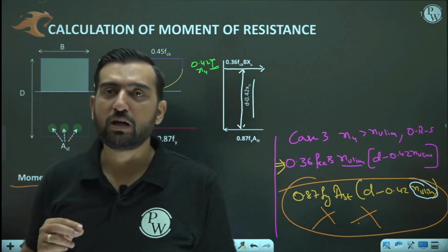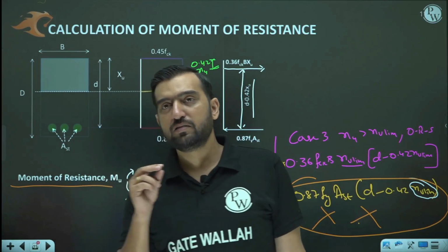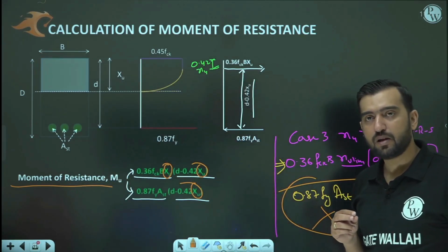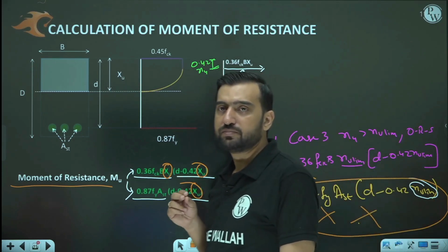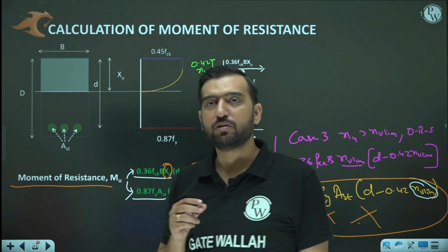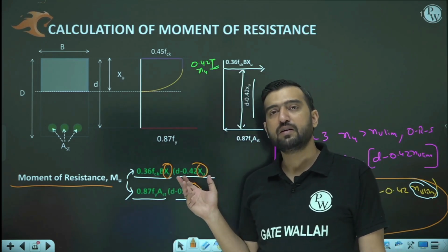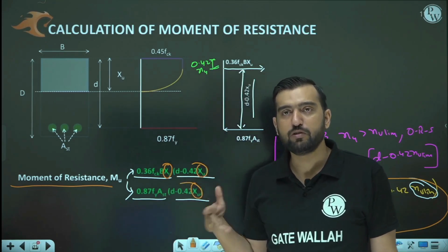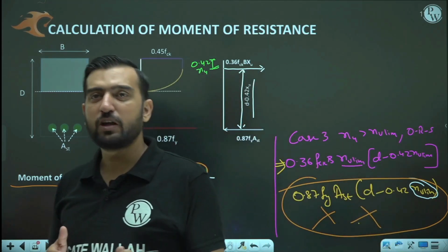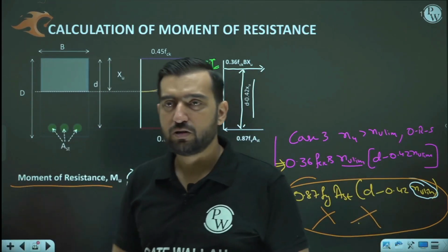And if you want to calculate the exact safe load, or you can say working load, then you can divide the W value with the appropriate partial factor of safety, which is generally 1.5 for dead load and imposed load, isn't it?